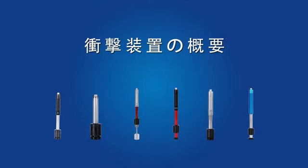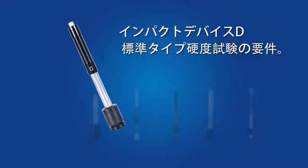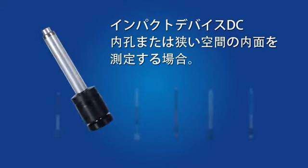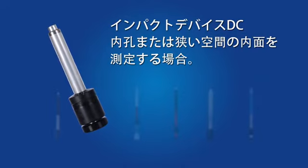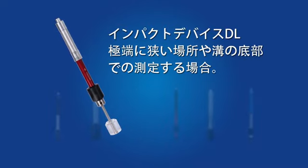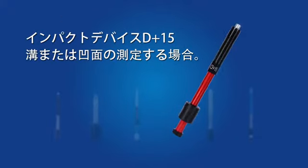Brief introduction to impact devices. Universal Impact Device D, for the majority of your hardness testing requirements. DC, used in very confined spaces, for example in holes, cylinders, or for internal measurements or assembled machines. DL, for measurements in extremely confined spaces or at the base of grooves.